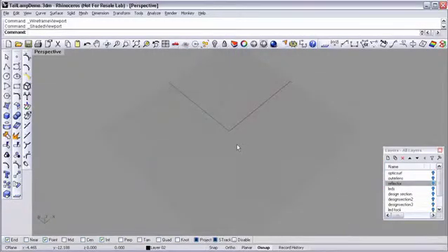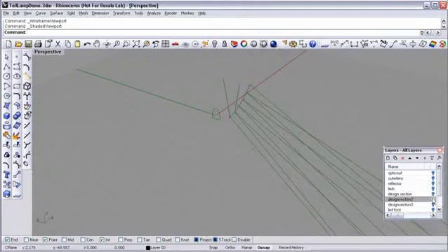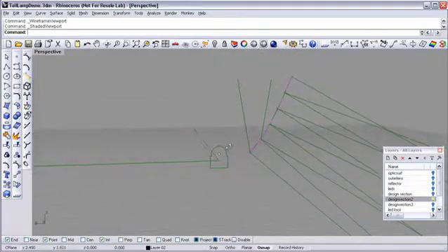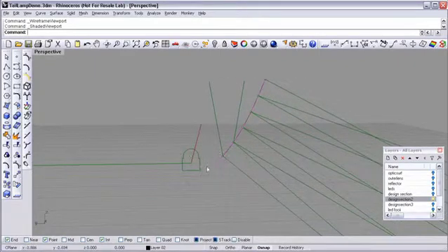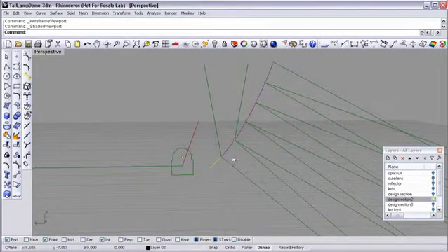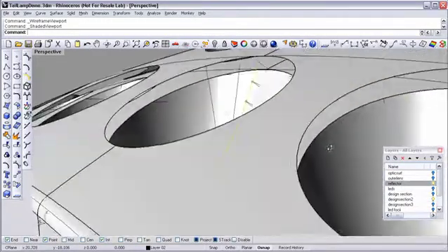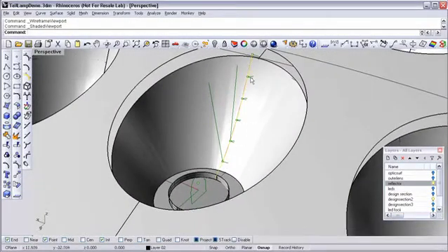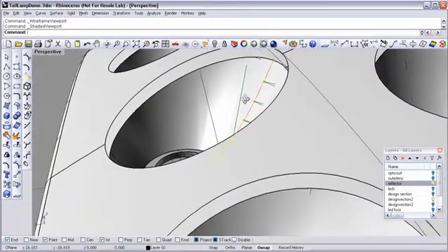Typically when we're designing these types of systems, we'll start with some sort of base shape, and we'll build optical facets onto that base shape. Right now, the line that I've highlighted is the base parabola. I'm going to turn the reflector back on for a second, and you can see where we're working. We're working in the center cup right now, and I've taken that base shape that they've given us, offset it a little bit, and I'm going to start designing facets into that component.